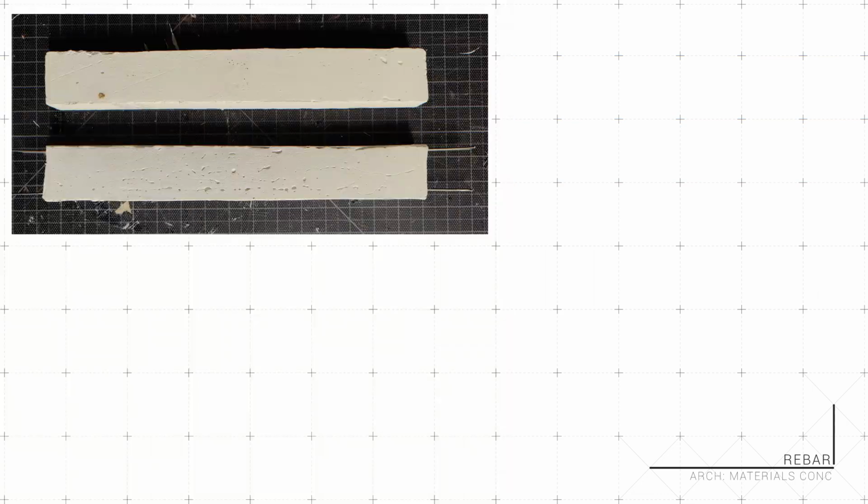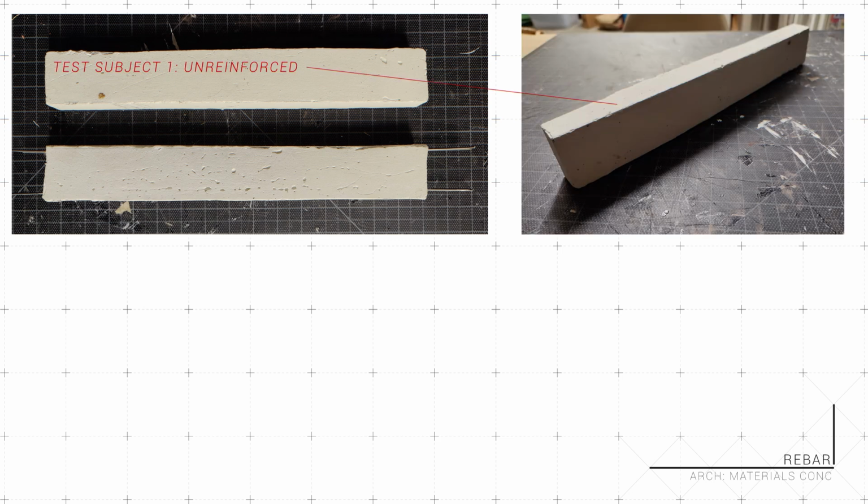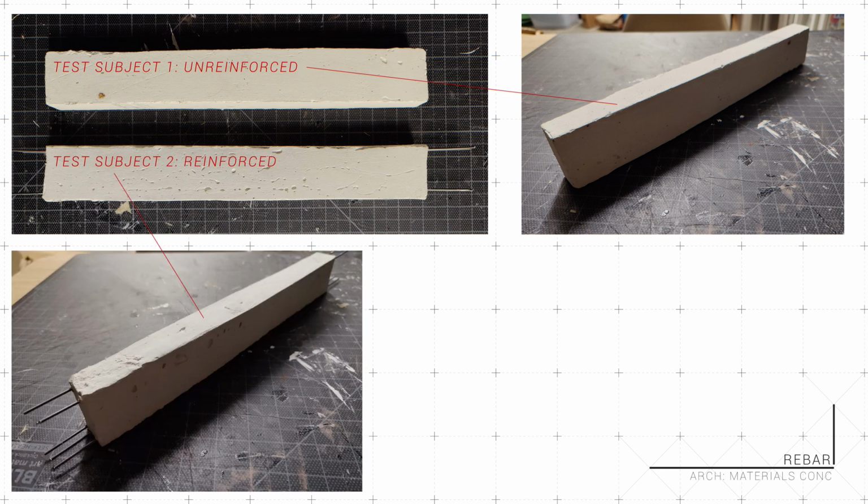For the sake of testing the tensile strength of reinforced versus non-reinforced beams, we will use not concrete, but plaster of Paris, still a cementitious material, but far less strong than concrete. Household items will break plaster. Test subject number 1 is a completely unreinforced plaster beam. Test subject 2 is similar but has thick wires inserted to act like rebar.